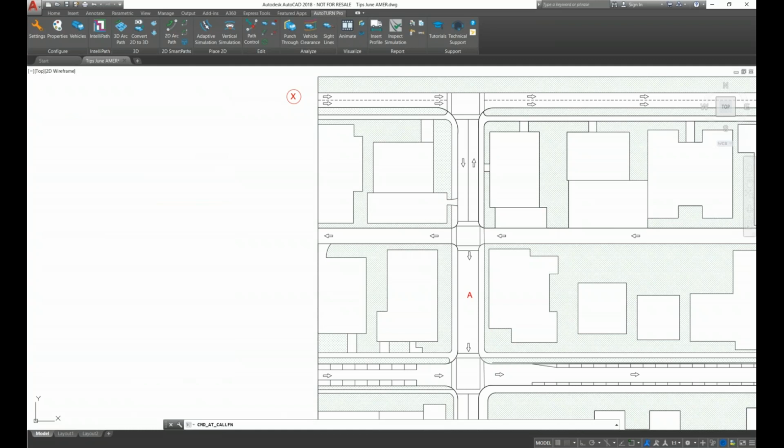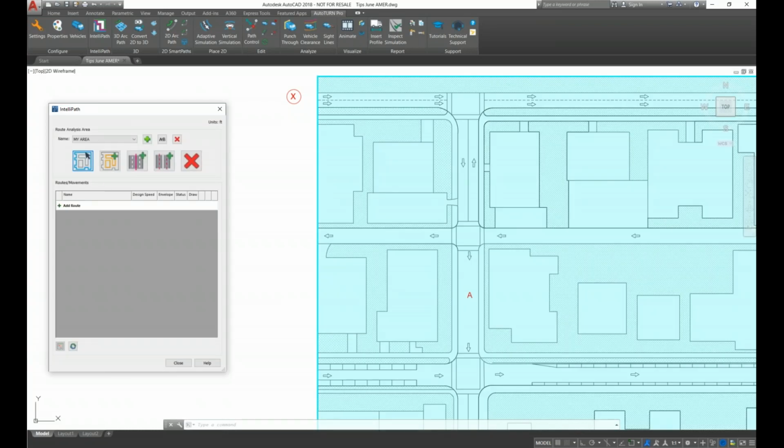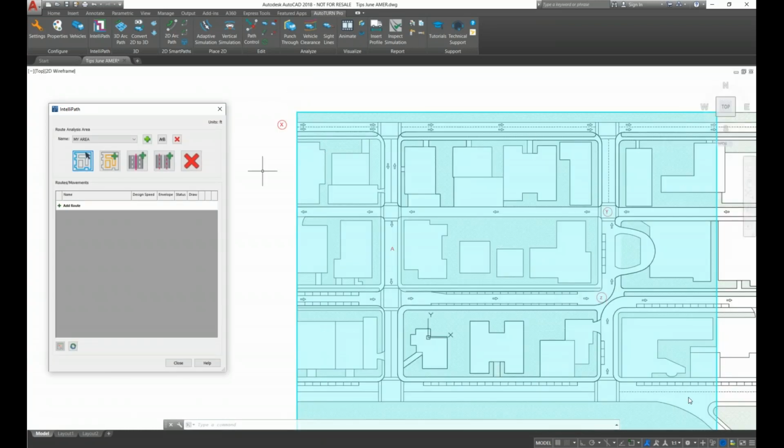So with the pick, the software recognizes this closed polyline, which I already created within the area, as the analysis area. So this can be a polyline. The software can detect a polyline, line, or a closed polyline, but it was always better and easier and faster for the software to detect a closed polyline. Hence, I created this scenario to make it easier for the software to detect.